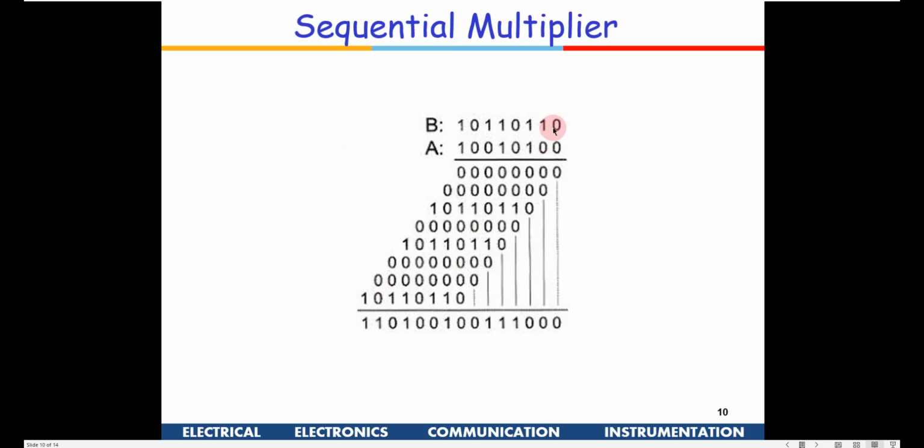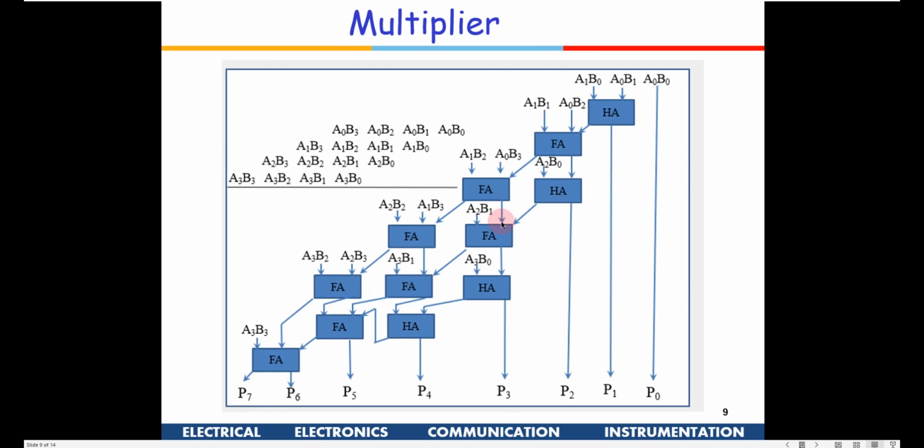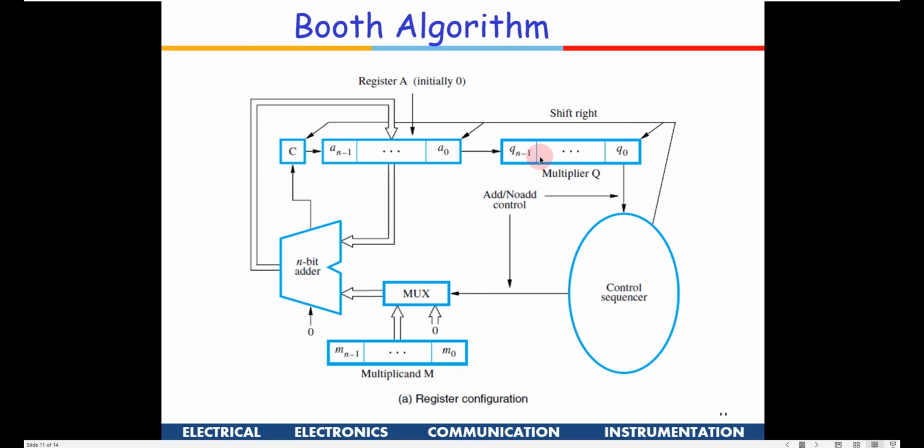So this is what this particular logic is implemented through hardware. If the bit is 0, I am adding 0. If the bit is 1, then I am adding this entire B, and then I am also shifting it. So I put the one data out here, the second data out here, and I take the first bit. If the first bit is 0, I add a 0 itself. If it is 1, then I will add this particular data out here, and then I shift the data.